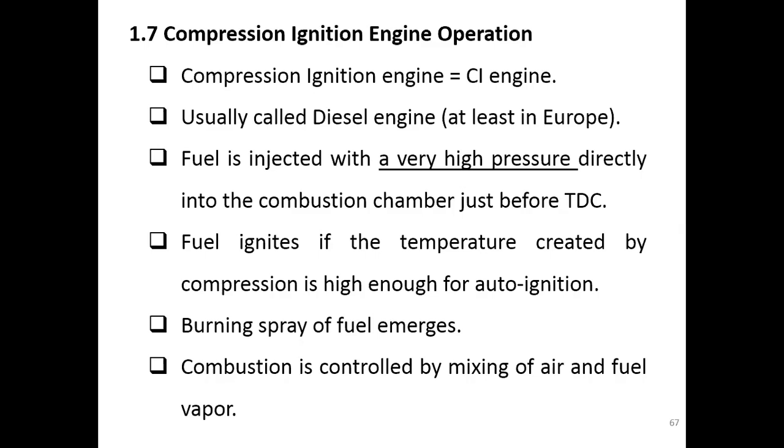So there is no question why this fuel has to be injected at a very high pressure, because inside the combustion chamber there is already air at high pressure. The fuel pressure has to be higher than that of the air. Then the fuel will ignite on the condition that the temperature created by the compression, or in other words the air temperature, is high enough for self ignition or auto ignition.